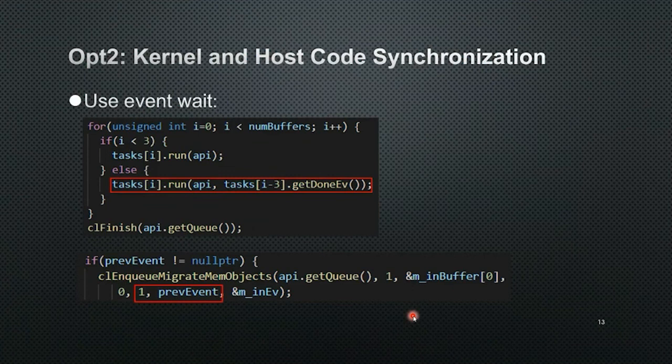Remember, in the class we discussed the AXI master first, and the number of outstanding read requests. The number of outstanding requests depends on the latency. So in order to maximize the data bus, you want to put in more outstanding transactions. But more outstanding transactions consume resources. In this case, you consume the data buffer.